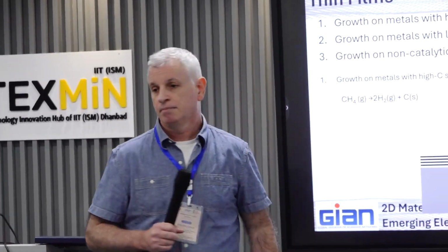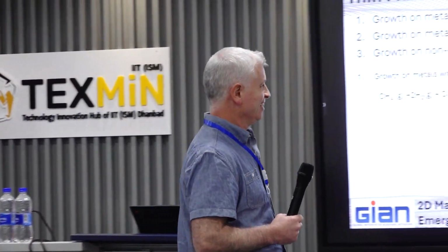So you want to say that with high carbon solubility, few layers will form? Yes. In a metal that has high solubility of carbon, you will most probably end up with a few layers of graphene, because it's very hard to control the number of layers when you have high solubility. So for making a single layer, then we need to...